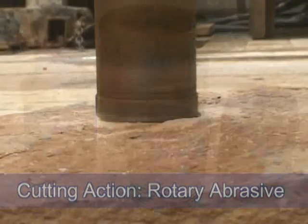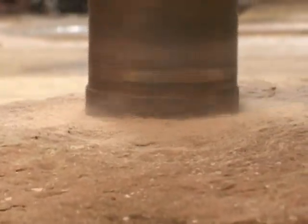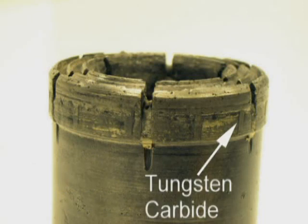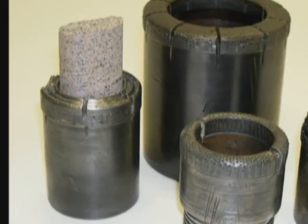The rotary abrasive cutting action uses 2 of the hardest substances available for bit construction, namely diamonds, both natural and synthetic, as well as tungsten carbide. These materials are bonded to the bottom face of the bit only. The bit's body consists of a round steel tube. This hollow design enables the open face of the bit to cut 2 surfaces at once, the inside face of the borehole and the outside face of the core sample.